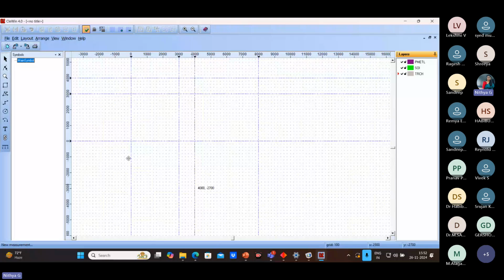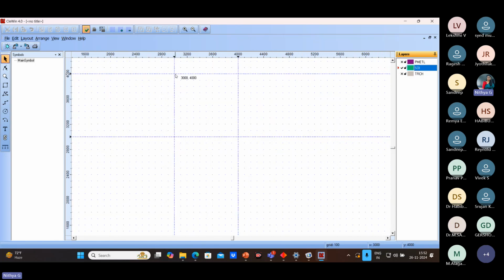So what do I do? This is 1,000 micrometer along the X and along the Y also 1,000. So basically it is a 1,000 micrometer area of the proof mass. I have to use the SOI layer, right? You are not requiring any other layers as of now. It is only the SOI layer. So choose the SOI layer and take the rectangle.